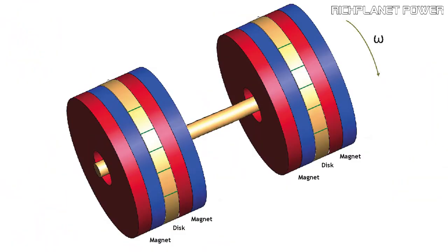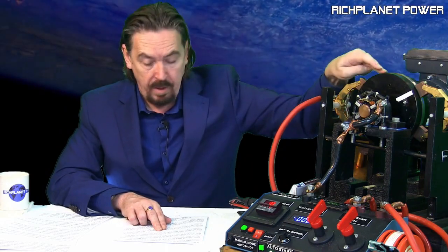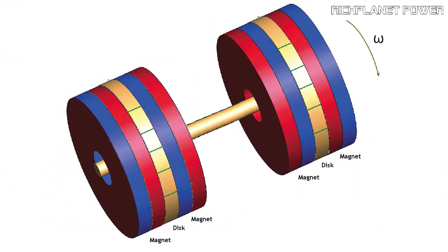If the magnets in each machine are placed with opposite polarities, so you've got the magnetic field going that way in one of them and then this way in the other, but they're on the same shaft, such that the field through each conducting disc is going in the opposite direction, one machine will have its positive terminal on the rim and its negative terminal on the shaft, whereas the other will have its negative terminal on the rim and the positive on the shaft.